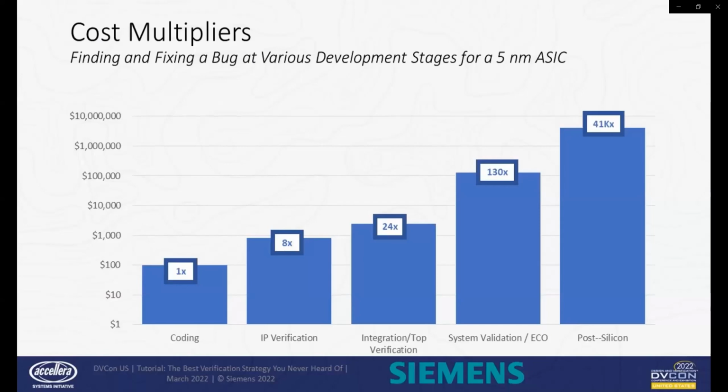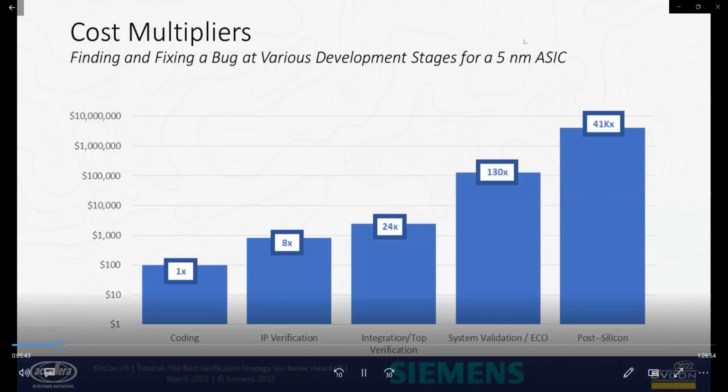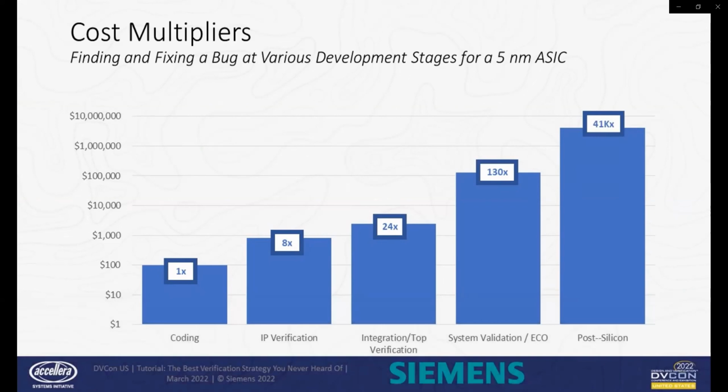An industry analysis of IC respin root causes has revealed cases where not only complex corner case bugs are escaping into production, but also trivial bugs. For example, even after billions of cycles of coverage-driven, constrained random simulation combined with directed testing, one high-end server project in the analysis experienced an out-of-range indexing error that resulted in data corruption. Now, this simple yet costly respin could have been avoided if the design engineer simply ran lint on the RTL code prior to checking it in.